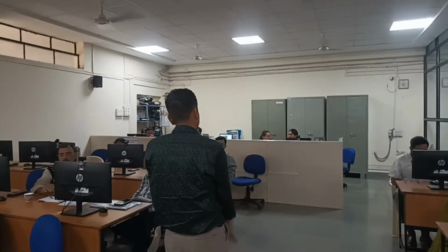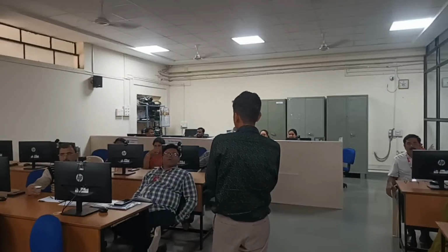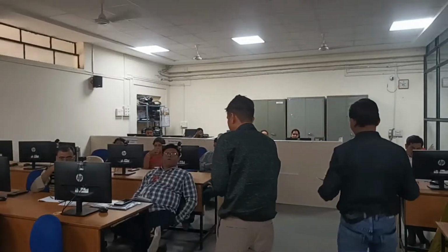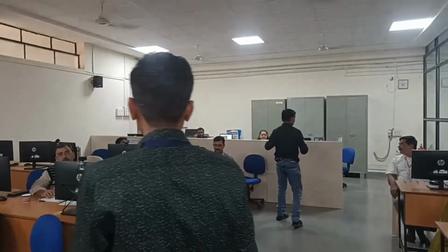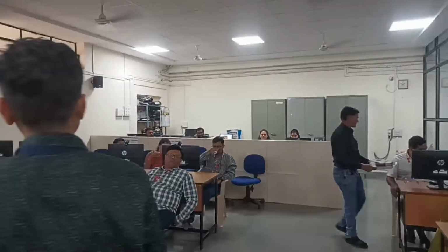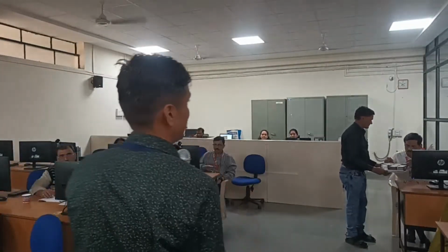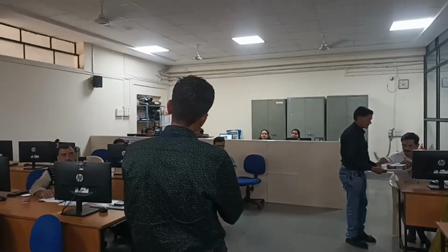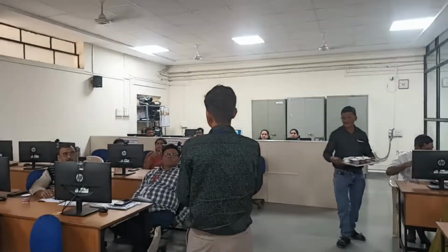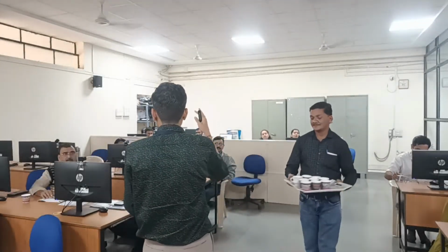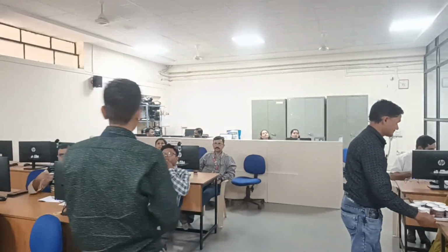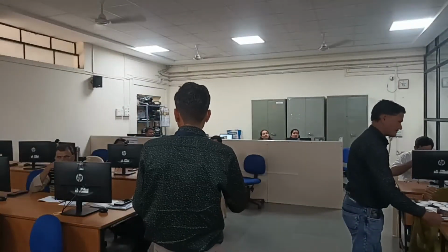So how do you tackle this? You have to normalize these impedances to one value and do the design calculation. This is nothing but a filter. Mind my words: input matching networks and output matching networks are nothing but filters. So you design filters. The only requirement is that your source impedance and load impedance will not be the same.